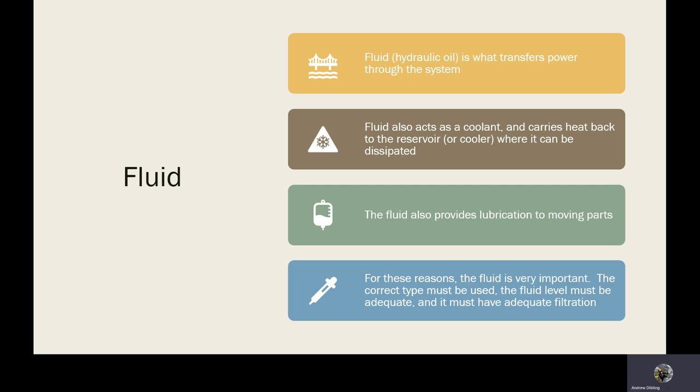One of the biggest problems with hydraulic systems, any hydraulic system, is incorrect oil use or the wrong type of fluid use. A lot of folks like to go with synthetics because they hear synthetics are the best thing since sliced bread in terms of oils. And normally they would be right. They keep their viscosity over a wide range of temperatures. They are almost oblivious to thermal breakdown. They're hydrophobic, which means they reject water. They don't absorb water. And none of these things can be said about mineral oil.